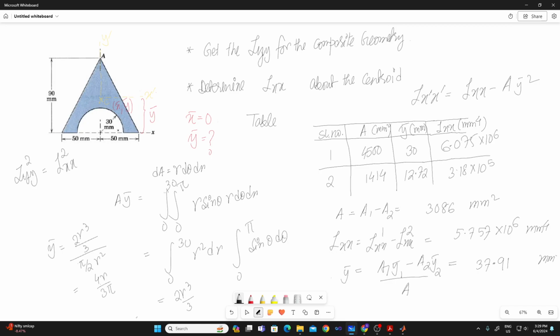If I take the quarter of a circle, the moment of inertia with respect to the x-axis and with respect to the y-axis is the same. If you take both sides, then it's just double. So for the global Cartesian, not the centroidal coordinate system, with origin at the center of the circle, this expression will be valid. Of course, for the centroidal coordinate system you will have to do all these manipulations that we have done here. Now for the triangle, I would suggest you do this.